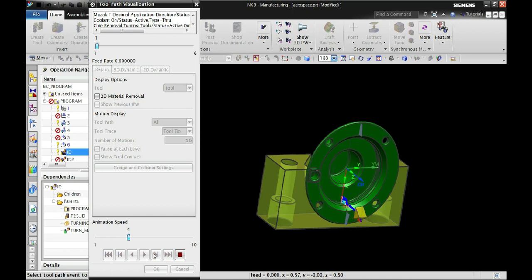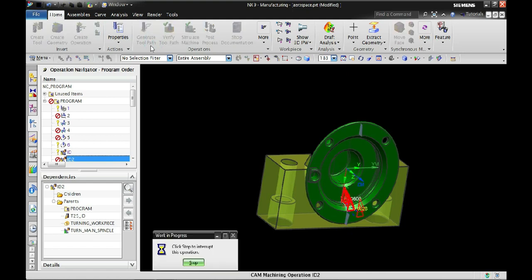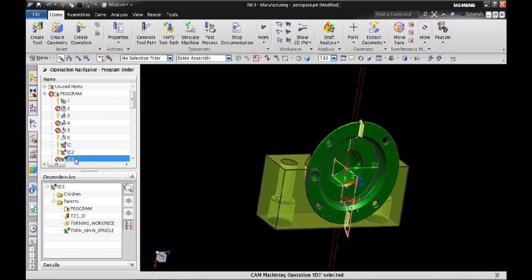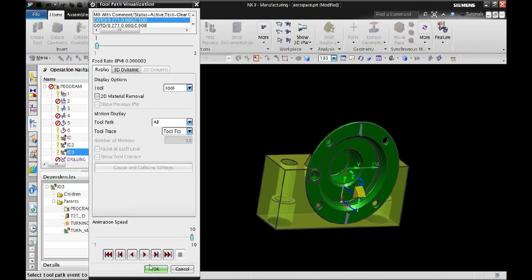In this case, we are using a triangle insert. Triangle will be better for a good lead angle. You have good chip clearance and stuff. You can see how it generates the toolpath. Just making the chamfer.